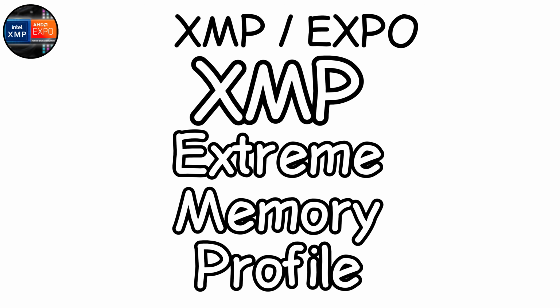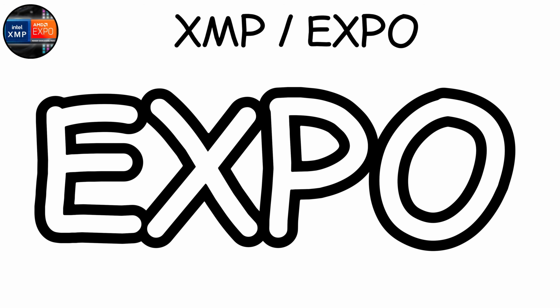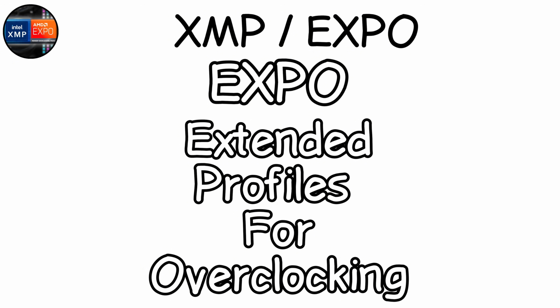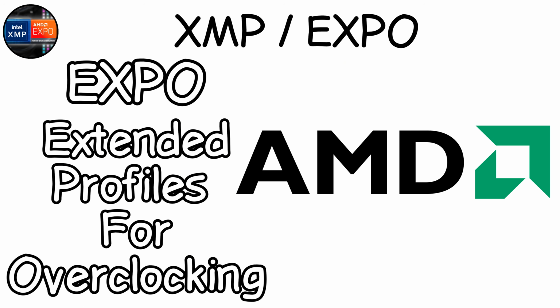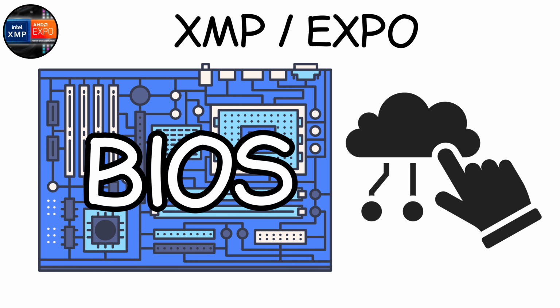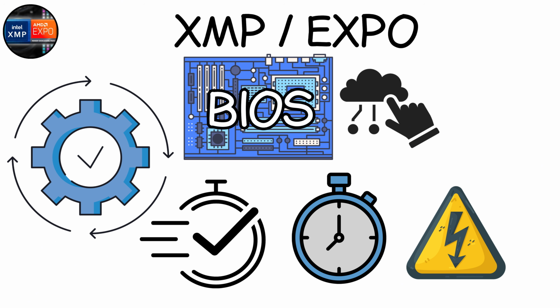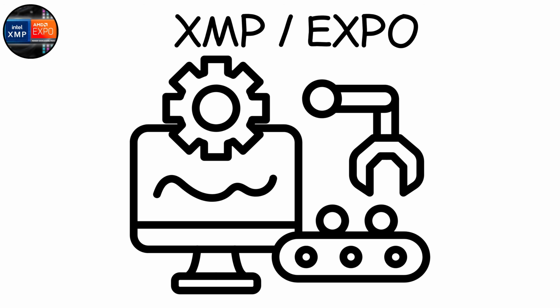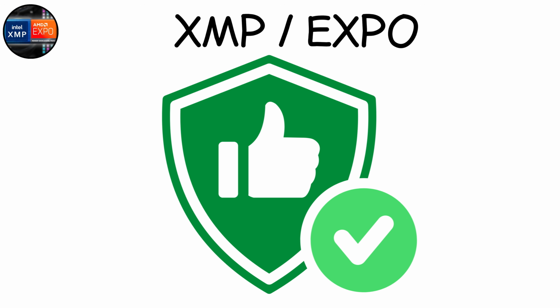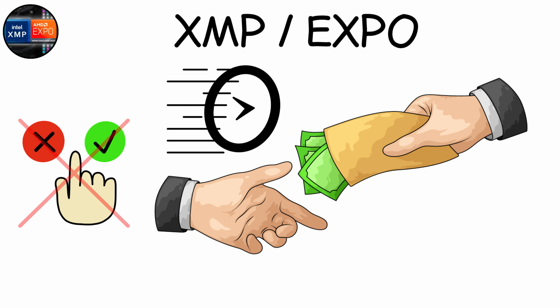XMP stands for Extreme Memory Profile and was created by Intel. EXPO stands for Extended Profiles for Overclocking and was created by AMD for DDR5. They do the same thing, but use different standards. Enabling the profile in your motherboard BIOS automatically sets the correct speed, timings, and voltage all at once. The manufacturer has already tested these settings extensively, so they're safe and stable. This is not optional if you want to use the speed you paid for.